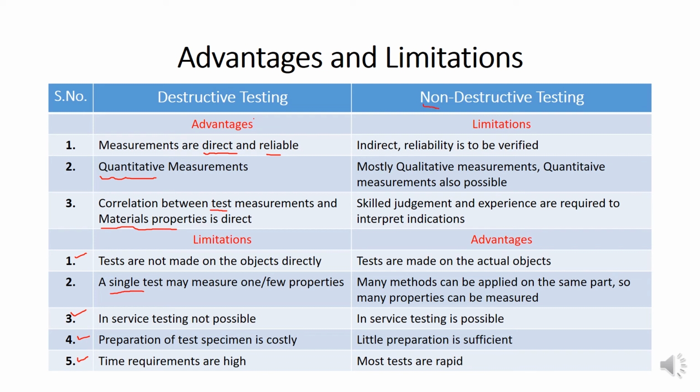And if we move on to non-destructive testing, its limitations are that it is indirect, and reliability is to be verified. It gives mostly qualitative results, that okay, a crack is present, but it will not give you exact information about the cracks.